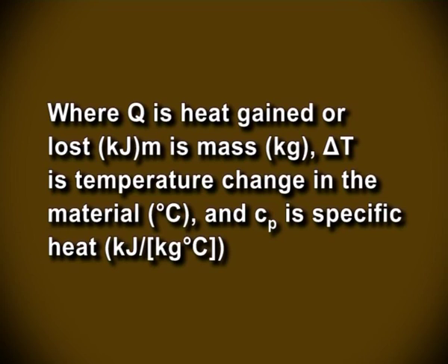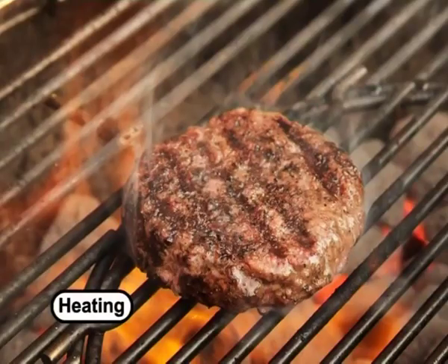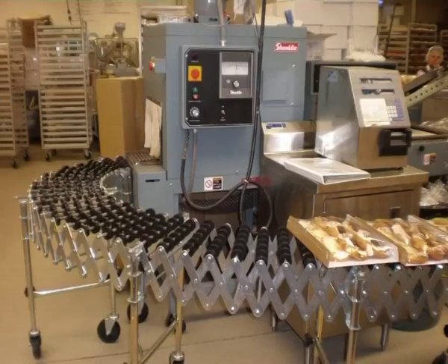Specific heat is an essential part of the thermal analysis of food processing or of the equipment used in heating or cooling of foods. With food materials, this property is a function of the various components that constitute a food, its moisture content, temperature, and pressure. The specific heat of a food increases as the product moisture content increases.